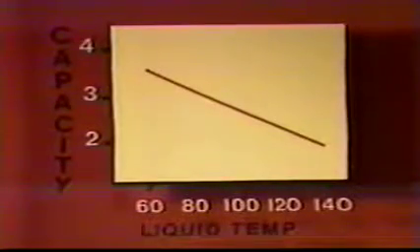As is the case with refrigerant type, a TEV can pass a given quantity of liquid but provide lower capacity because the inlet liquid temperature is too high. As a general rule, as liquid temperature goes up, capacity goes down. Valve capacity can vary as much as 20% from nominal as inlet temperature varies from rated conditions. More on rating conditions in a few minutes.